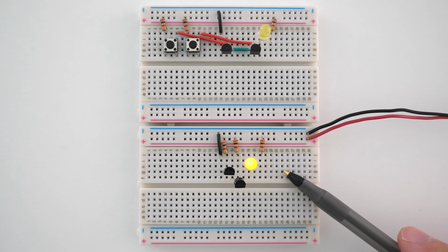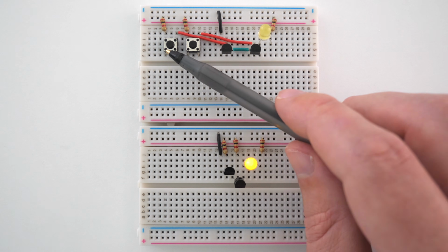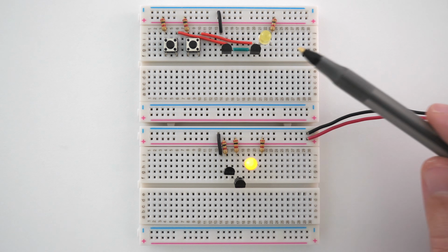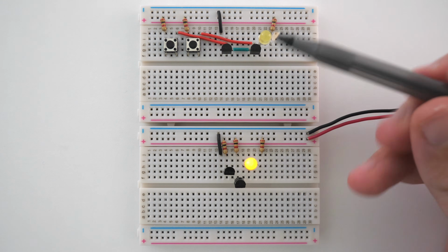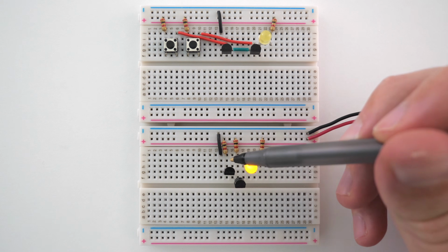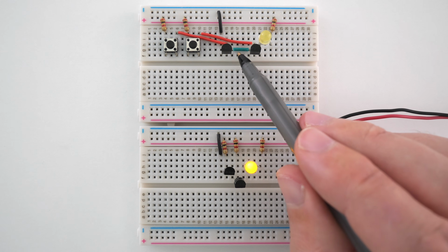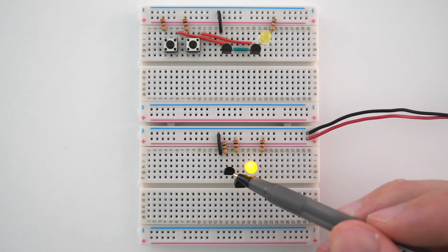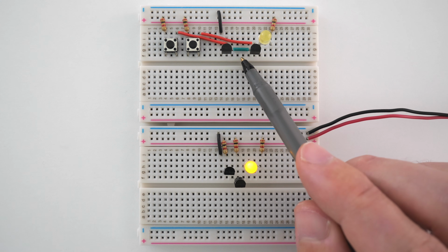These are actually built the same way, except AND gate 1 has a whole bunch of extra components. AND gate 1 has these switches and these red wires, and rather than use the switches and red wires, we can just connect the base of each transistor directly to the positive 5 volt rail by going across the resistor and then directly into the base of each transistor. And rather than have this green wire, we can just connect the collector of transistor 1 in the same line as the emitter of transistor 2, and this allows these to be electrically connected without having the green wire.